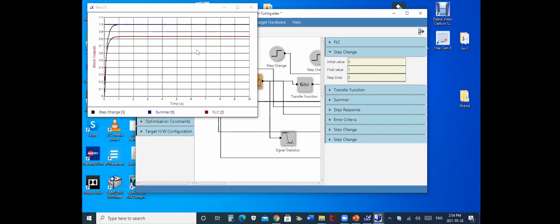Sorry, the question was the relevance. So I was saying, you were mentioning before that other people who tune fuzzy logic only tune the membership functions. They do not tune the rules. They work out some sort of rules and then put them in the system, and then they tune the membership functions only. Well, that will give you some combination, but not necessarily the optimum. Obviously, the optimum will be when you put all the rules, membership functions, gains, and scaling factors together and tune them.